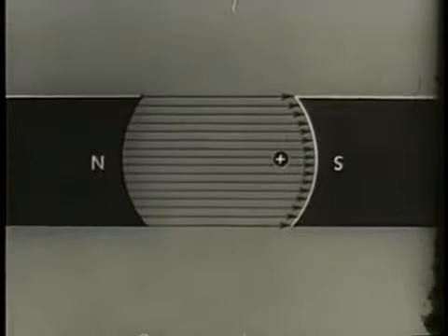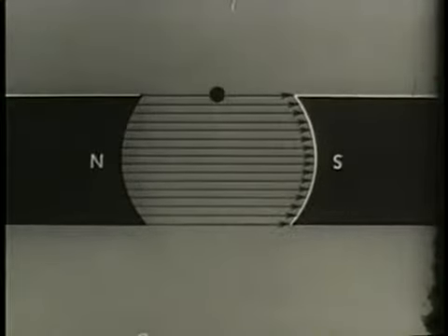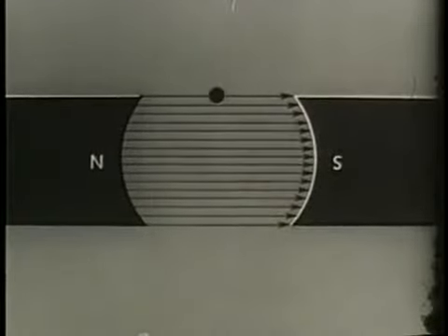As the conductor keeps turning, the number of lines cut increases, so that at a quarter turn or 90 degrees, the maximum number is being cut and maximum EMF is generated. Again, at 180 degrees, no lines are cut, no EMF. We reach a maximum again at 270 degrees, and finally, again at 360 degrees, no lines are cut. The conductor has rotated 360 mechanical degrees, which correspond in this instance to 360 electrical degrees.